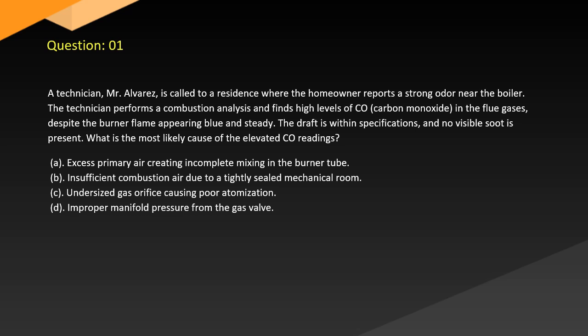Question 1. A technician, Mr. Alvarez, is called to a residence where the homeowner reports a strong odor near the boiler. The technician performs a combustion analysis and finds high levels of carbon monoxide in the flue gases, despite the burner flame appearing blue and steady. The draft is within specifications and no visible soot is present. What is the most likely cause of the elevated readings?